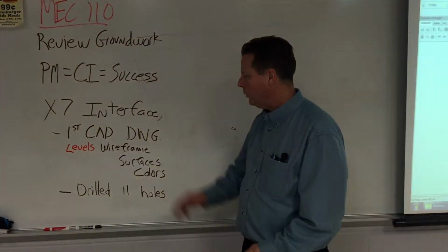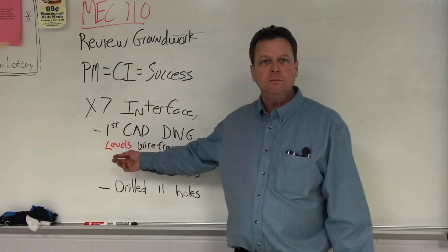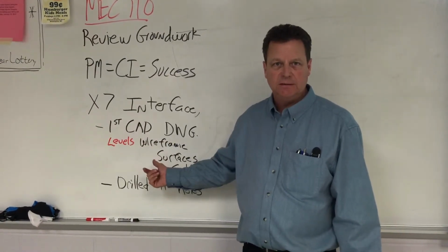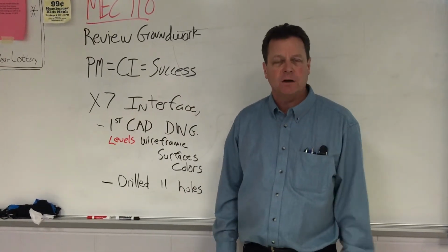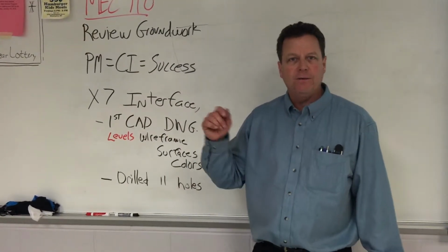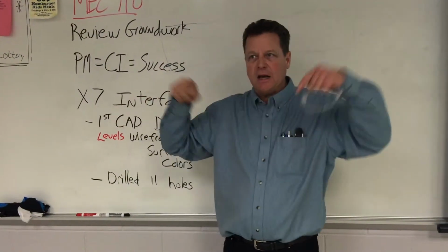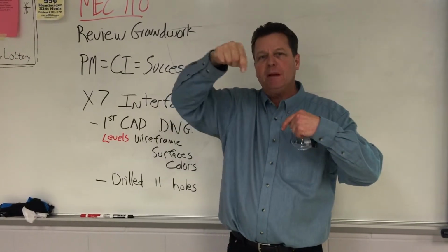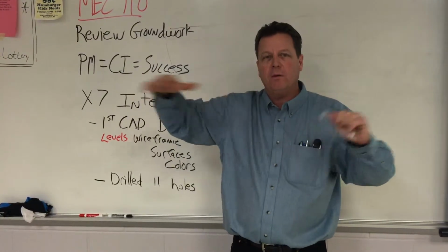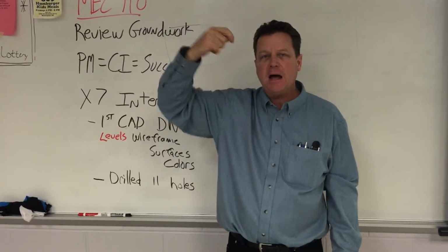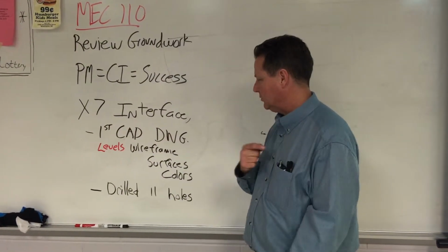After we got all the geometry done, we made another level at the bottom for surfaces. And then we went over how you create surfaces to get a watertight model, for lack of a better word. And we learned that the flat boundary tool can also be the outside of the box, and the other boundaries would be all the holes. So as long as you chain the outside geometry and each one of the holes, it would fill in the surface and not fill in the holes. We also went around the outside of the part. I'm going to show you that in a minute.